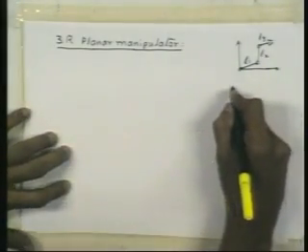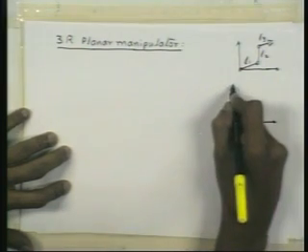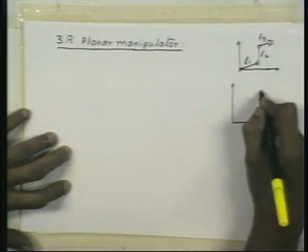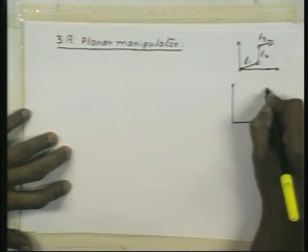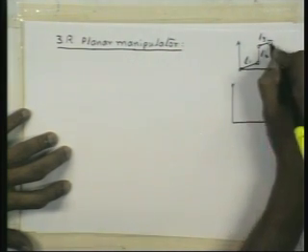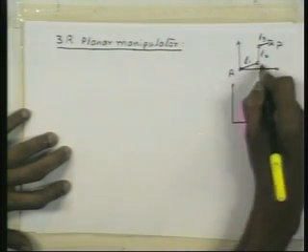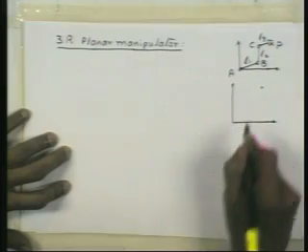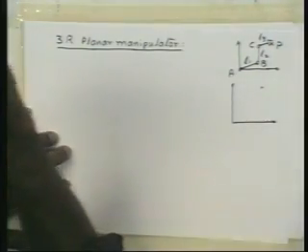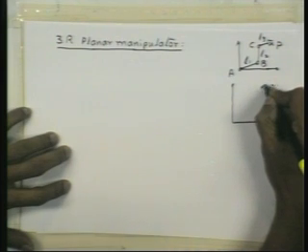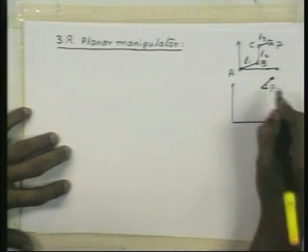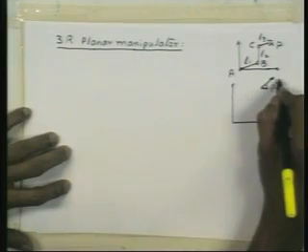So what is given here are these link lengths and the fact that the end effector, this special point P, so this is A, B, C, this particular point P on the end effector, is typically called a reference point, which was used for defining workspace. If you remember, reachable workspace was defined using a point on the end effector. Right? So this particular point P is here, and the direction of the link has to be this, which essentially is given by this angle. So position of P and the angle alpha are what are given.